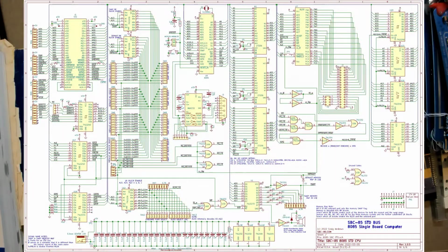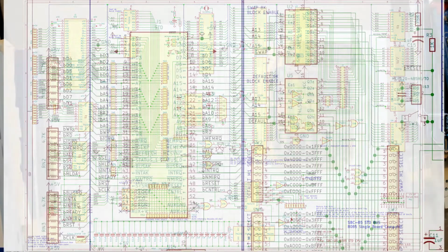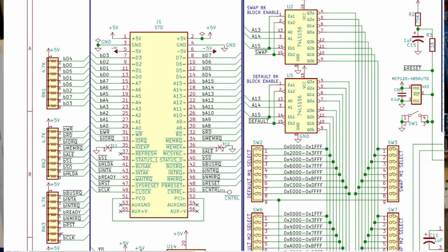You might want to patch this to an onboard signal, such as the not onboard read, and then use it on a memory expansion card as part of its address decoding. Or you could connect them to the outputs of the onboard output port, and that would allow you to use that output port to page an external card or something.